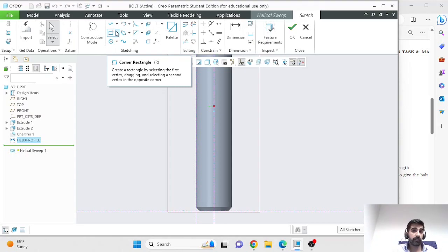We are removing threads from it, which is incidentally similar to how you actually make threads on a cylindrical feature using a die, which we saw in the class. A die has thread cutting teeth on its inside, and you run it on a cylindrical member. It removes material, and the major diameter would be the same as the original diameter of the feature, and the minor diameter is determined by the profile of the threads on that die.